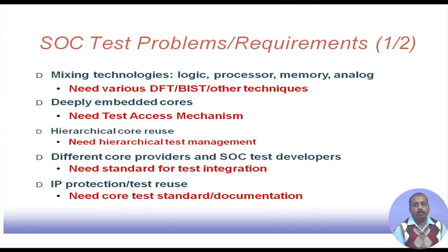So, this is another problem, because the core vendors, or core providers, have their own design, they have done their own test pattern generation or BIST or whatever it is, or some DFT structure. But now after that it is given to the integrator, and the integrator's group will also have the test developers who are working on the SOC test development work.